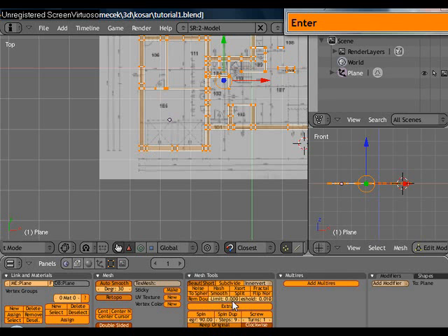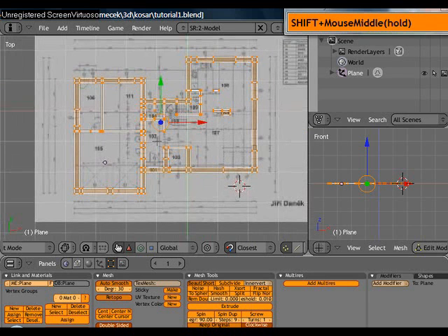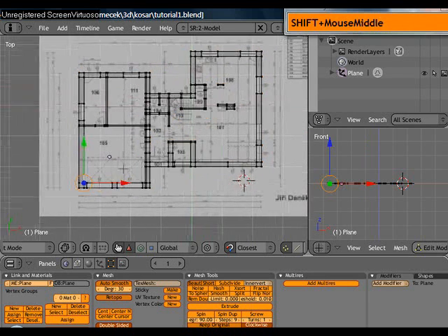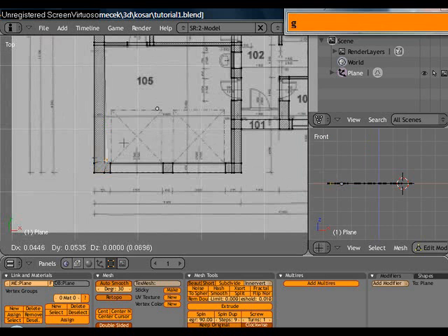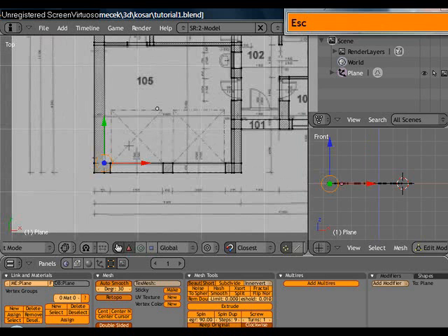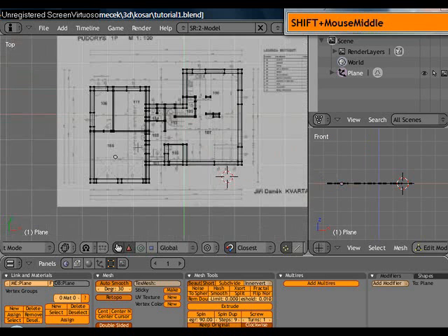It will mess up my geometry. So I set the limit to 0, remove doubles, and as you see, it's removed 4 vertices. So it's removed those two over here and those two over there. So now it's finished. As you can see, if I'm here and press G, I'm moving the whole corner, and I can start extruding up.